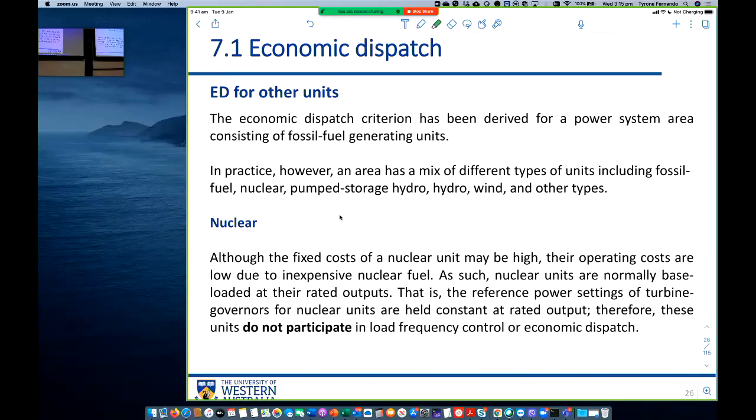Renewable energy can only be a dispatchable source if it's combined with a battery, so that when there is excess energy, it's stored, and when the source is producing less than the requirement, the battery kicks in and provides the difference. Because dispatchable means what is requested, what is allocated for a particular generator, it needs to supply.